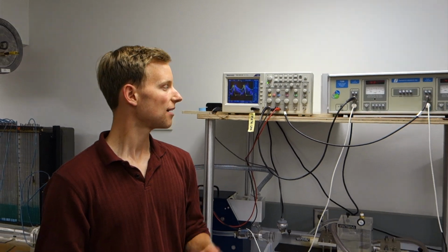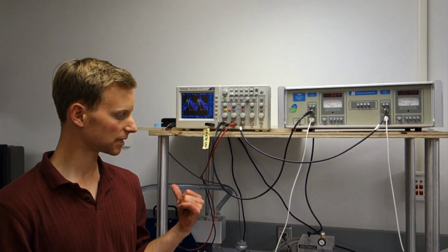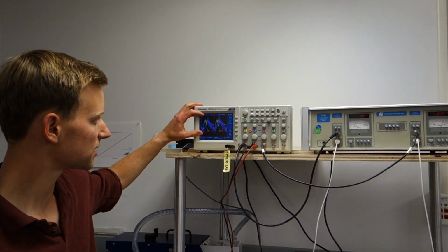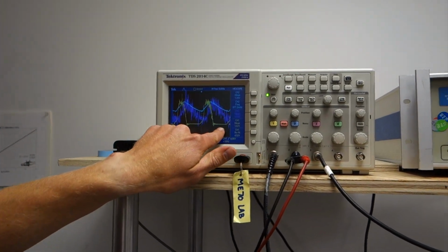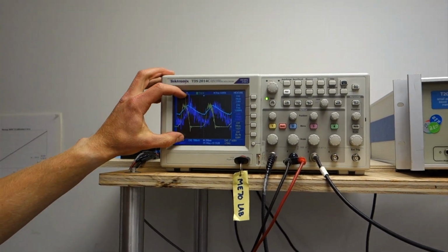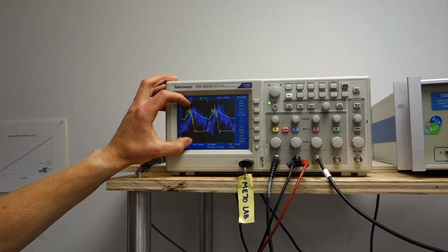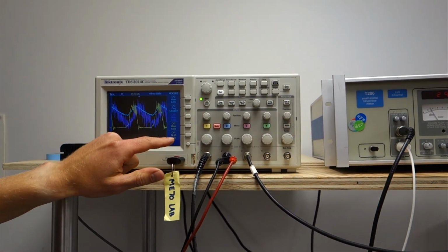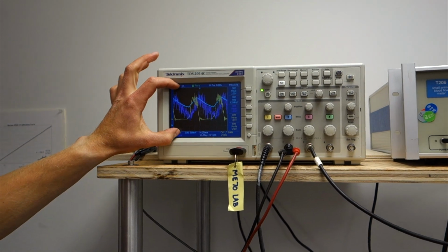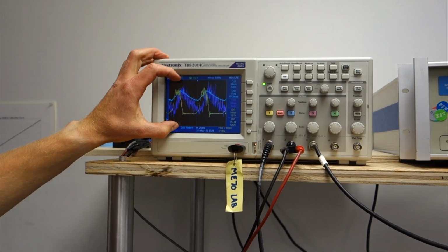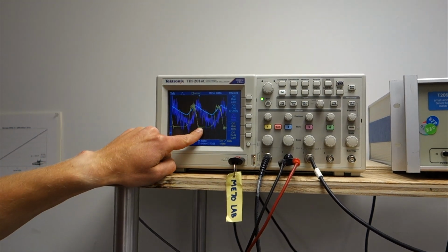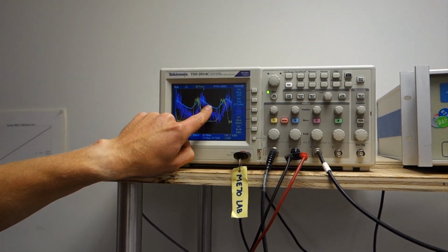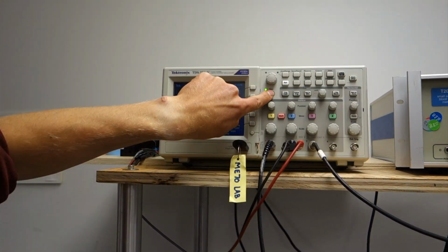All right, now it's time to take some data. So we have this USB stick in here. We've got the experiment running, and we have the oscilloscope set to have at least one period of data, preferably 2 or more periods, and the amplitudes are all pretty generous so that we have as much data as possible. When we press the save button here, we're going to be capturing all the data that's on one screen. So we want to have as much data as possible on one screen. And remember what I'm doing here, I'm going to use the yellow trace to back out what the blue trace will be. And I'll press save.